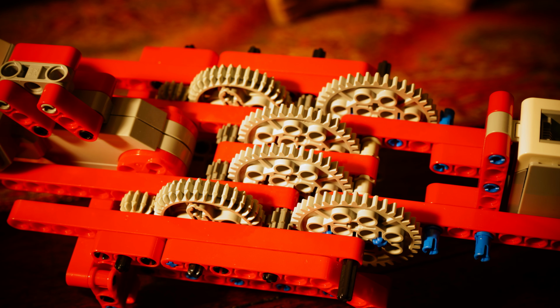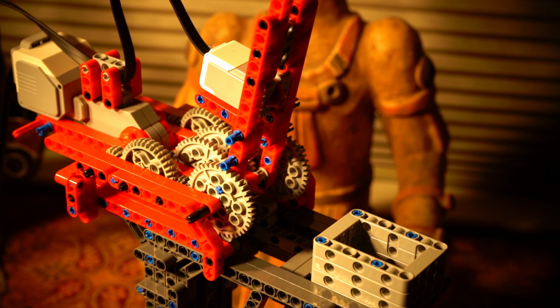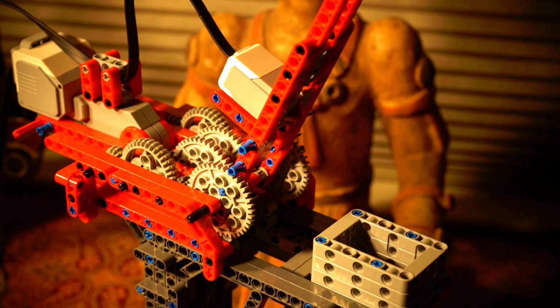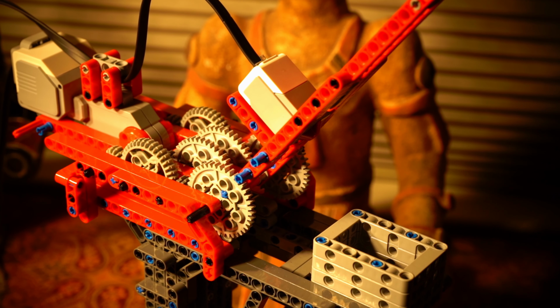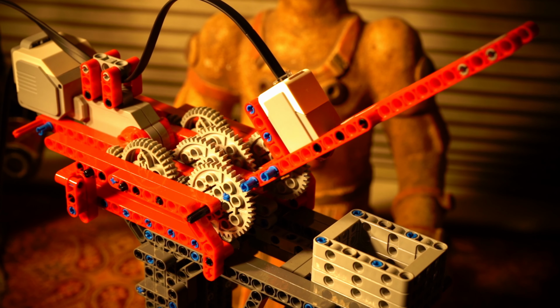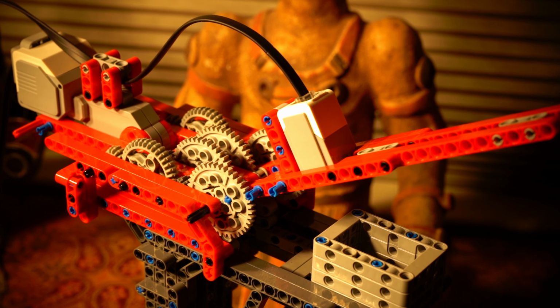This compound gear train has a gear ratio of 28:12, 40:8, and 40:8, so the cumulative gear ratio is 58 1/3 to 1. Note that as speed and torque are inversely proportional, the 40-tooth compound gear connected to the lift arm moves exceedingly slow as compared to the driver gear on the servo motor. This is the cost of torque, and why LEGO models that move heavy loads are often shown as time-lapse videos, because they take forever to complete their tasks.